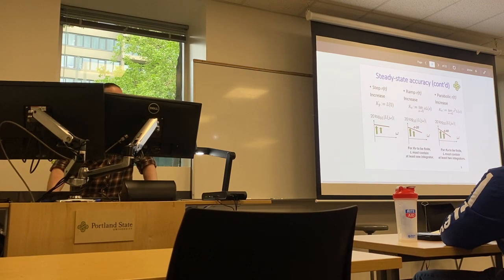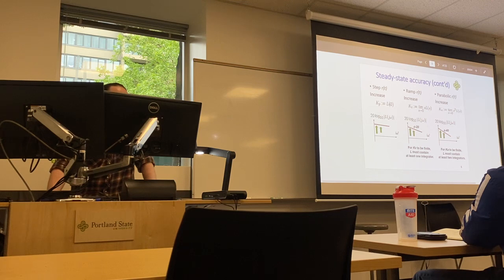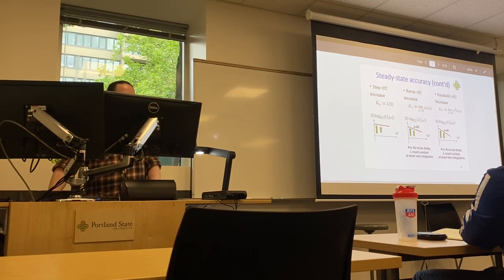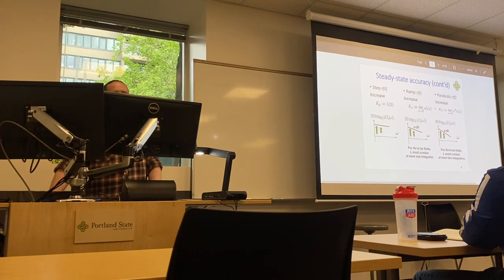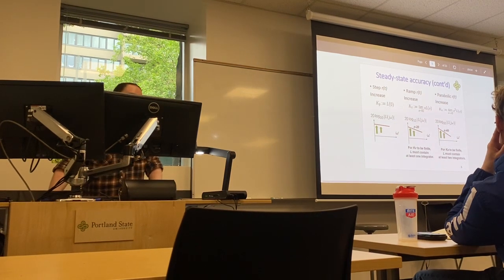We're continuing here, so we're looking at the step response. So if we have an increase here, we take the L of 0, we're looking at the initial value. So the limit as s approaches 0, so that's L of 0. If we have a high gain, then we have high accuracy in this case. We're responding to our ramp input. We would need to have at least one integrator for KB to be a finite value.